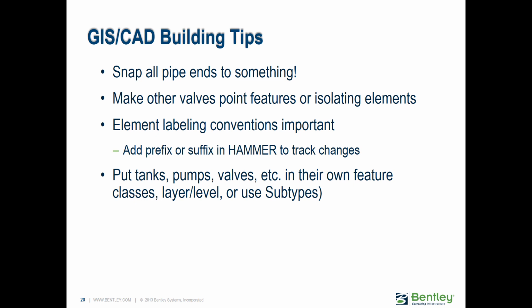And if you need to track changes to something, you can add a prefix to the beginning of the element label, and that's done through the flex table. So if you wanted to import data from Model Builder and then add some prefix or suffix to everything, there is a tool in the flex tables that allows you to relabel. And then also tanks, pumps, valves, they should all be in their own table.